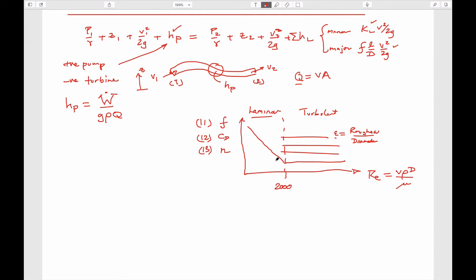And these are laminar behaviors, where this is some coefficient divided by Reynolds number, a constant divided by Reynolds number. The magnitudes of the friction factors, or drag coefficients, or Manning's formula coefficients, are constant in the regime where they're turbulent. Almost all the flows in open channel flows are turbulent, and so you can use a constant magnitude of this. They aren't necessarily that way for flow in pipes and for flow around objects. And so that's worth remembering.